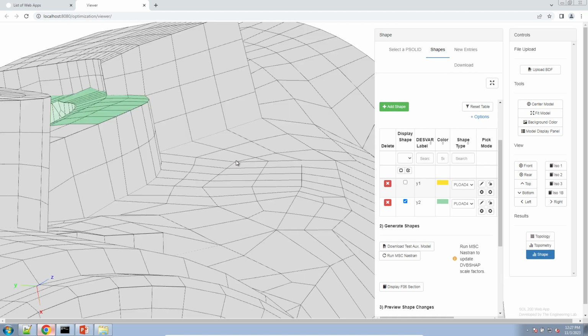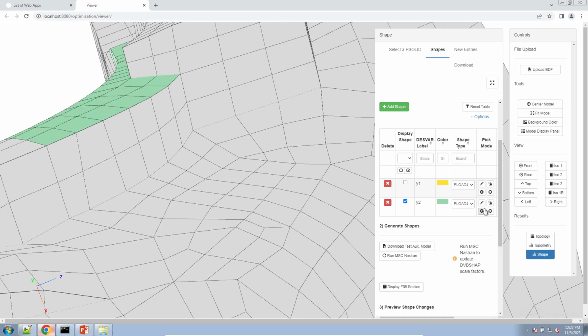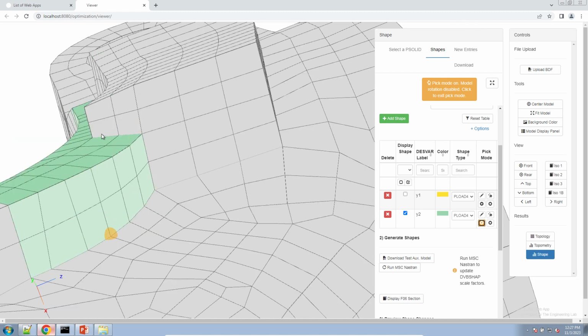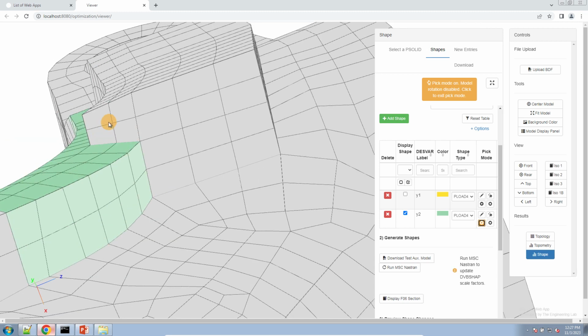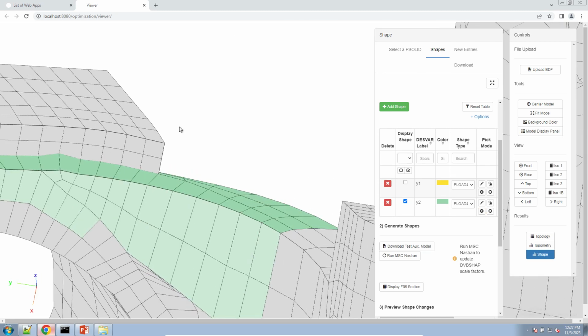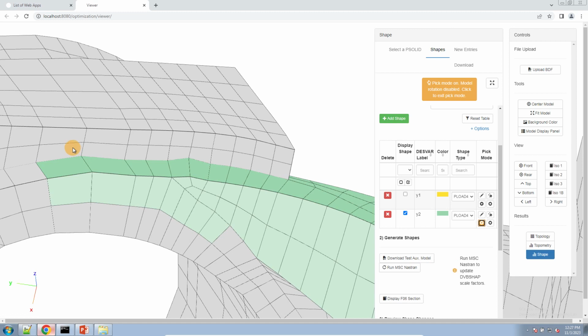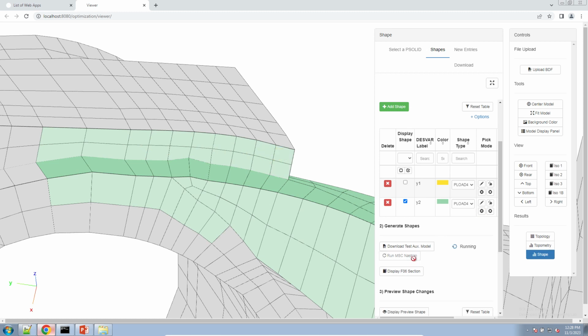Let's go ahead and rotate the model again. It's going to repeat the process for the other side. So here for the other side, I'm going to select these element faces that are going to be allowed to expand and contract. And then here we'll do the same for these element faces. Basically, generally, for any adjacent faces that are going to expand or contract, you also want to set the adjacent faces as secondary faces that are going to expand or contract.